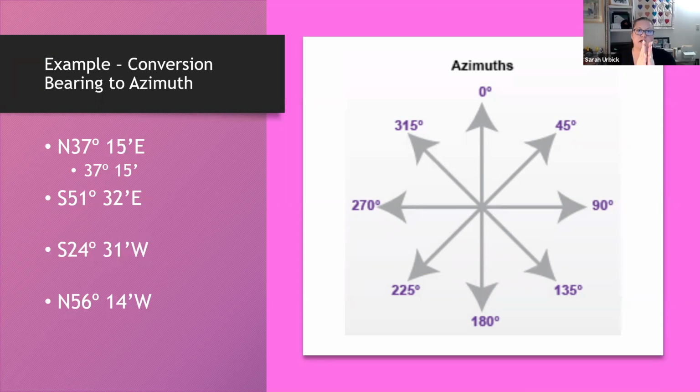So when we measure that way, we're actually measuring back towards the east, right? So our angle right in here, see my thumbs? Can't fill it in very well without breaking my angles. This is 51 degrees, 32 minutes. So what's my azimuth? From north, going clockwise.